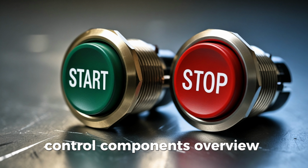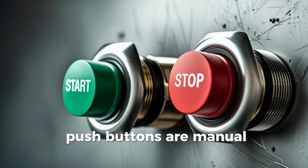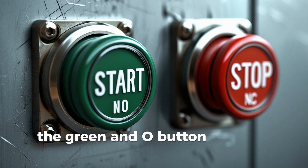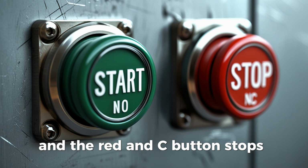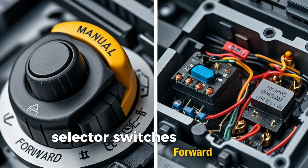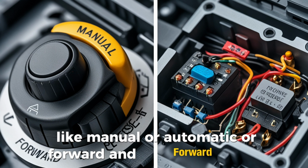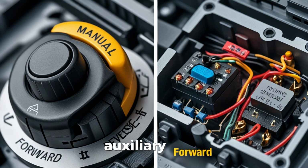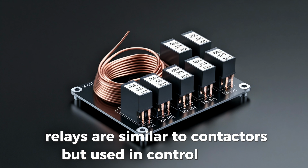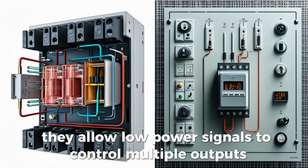Control components overview. 1. Push buttons. Push buttons are manual switches that control the operation of a circuit. The green NO button starts the motor and the red NC button stops it. 2. Selector switches. Selector switches are used to choose between different modes, like manual or automatic, or forward and reverse directions. 3. Auxiliary relays. Relays are similar to contactors but used in control circuits.